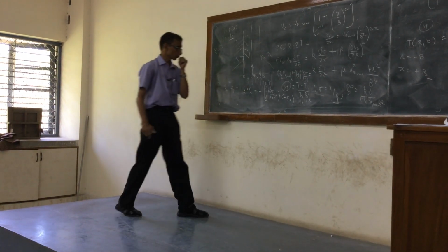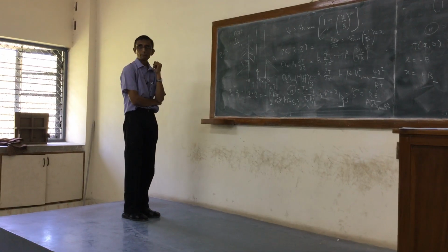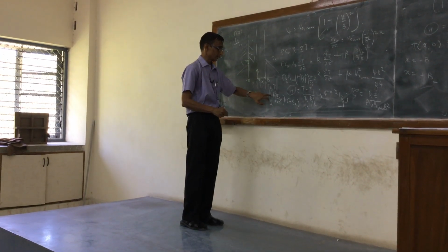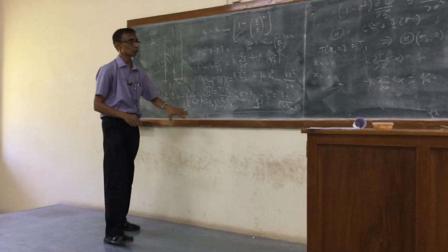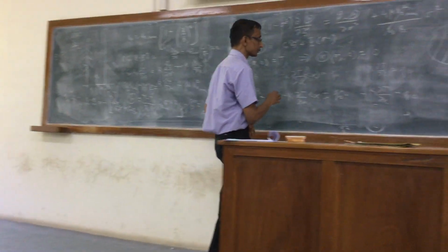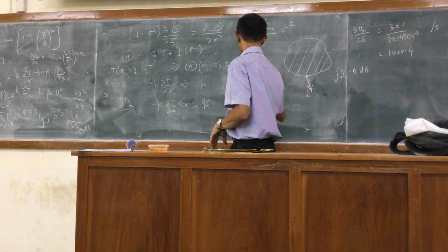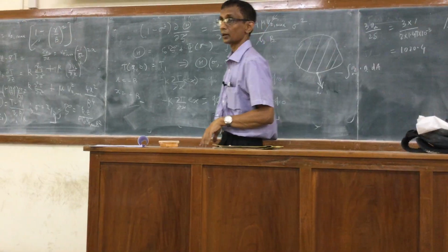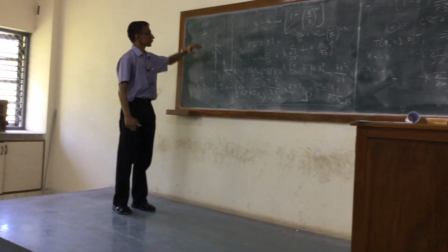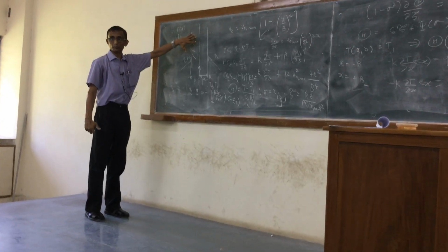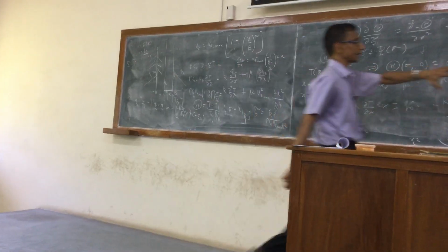And so how many minuses are there? Three minuses. There's a minus here, there's a minus here, there's a minus here. So it will be minus. So q naught is actually minus k dT by dx at x equal to minus b. Did we get a minus sign from minus q dot n? No, that is the formula, because that is being transmitted into the fluid. That is the heat entering the fluid, so that is automatically taken care of.